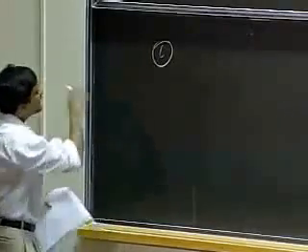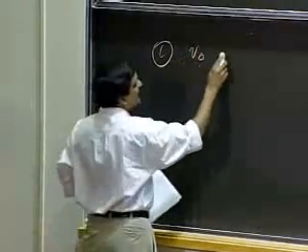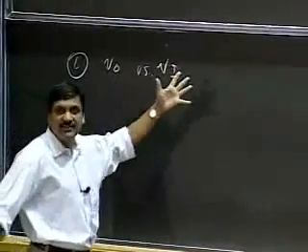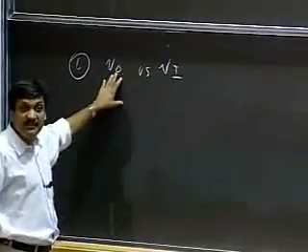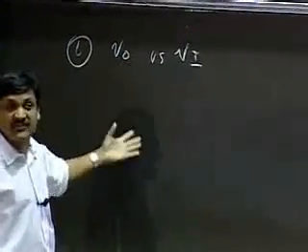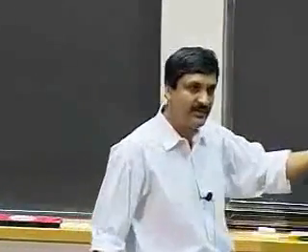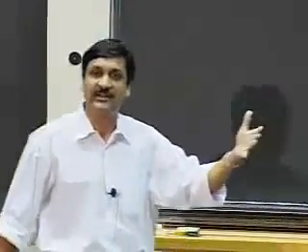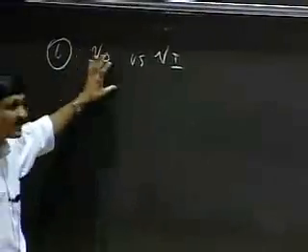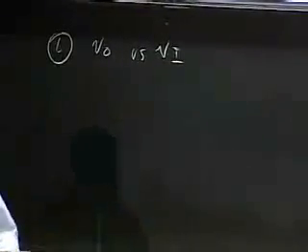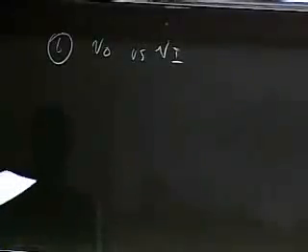Okay, so the first step, as I mentioned earlier, is to get the V0 versus VI. And in general, for some circuit that you build, the output may not even be a voltage. There are certain circuits where the output might be some kind of a current. Let's say I'm building a circuit where I'd like the current through some edge of the circuit to depend on some input. In that case, the transfer function would be the output current versus VI. And if I had an input current here, it would be output current versus input current, whatever the given problem tells you.